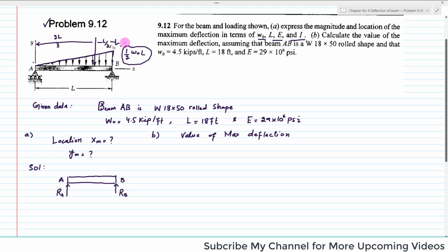So I will mention this load over here: the load is 1/2 W0 into L, acting at a distance of L by 3. This is the total length L. Clear? So you will use this beam as a free body diagram and you will find the unknown reactions. Clear?